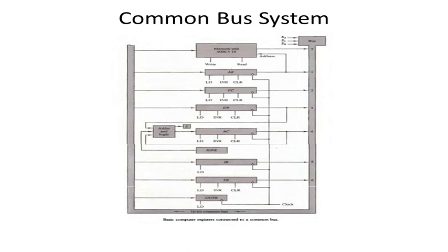This multiplexer will select any one of the registers, through which the data will be transferred to or from the register. Here the bus multiplexer has selection inputs S2, S1, S0. This is a 3-bit multiplexer, so 3 inputs give 8 outputs. So 8 registers can be selected based on the input. Suppose the input is 1, 1, 1, it is 7, then the memory will be selected. Once it is selected, either write or read operations will be performed.